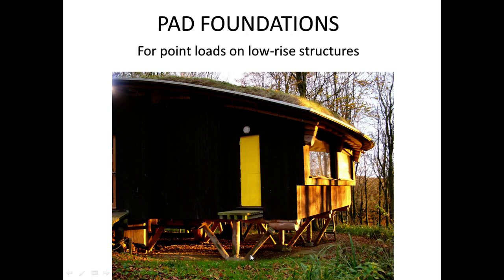These pads probably go into the ground not much more than a meter, I would say. Probably about a cubic meter of concrete on each of them. They're proud of the ground, which is quite nice. Again, that's a nice detail because we know that timber doesn't like to get wet, does it? So we don't want, or at least not saturated, so we don't want the timber touching the ground. So they're just proud, allowing the timber to connect just above the ground.